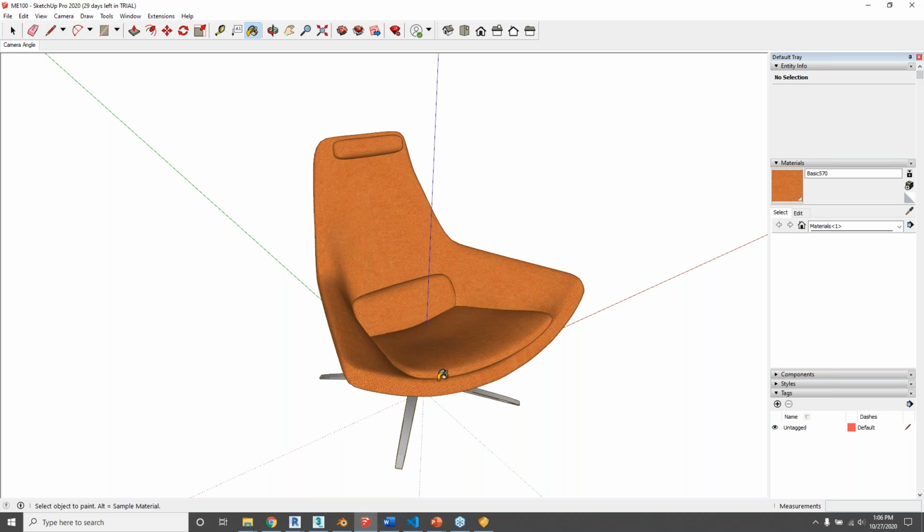So SketchUp Warehouse will often have, hopefully, below 20,000 polygons, which is what you want to aim at, but definitely not millions. And it happens often when you download a model from 3D Sky that it's in the millions of polygons, and that puts you so far from where you want to be that now it's just a lot of work cleaning it up.